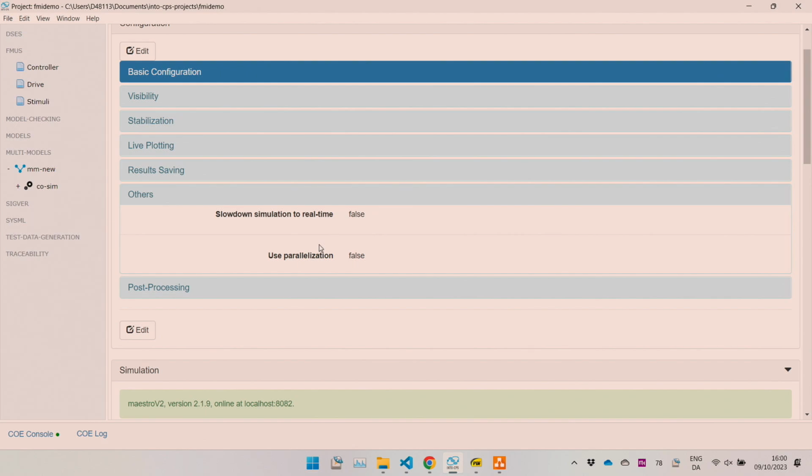of orders of magnitude higher than this co-simulation step. So they're much more accurate. But the problem is this co-simulation step. And if we tune down that step to the solver step, then theoretically it's more expensive. In theory, as you take the limit of this co-simulation step towards 0, you should get more and more accurate results.